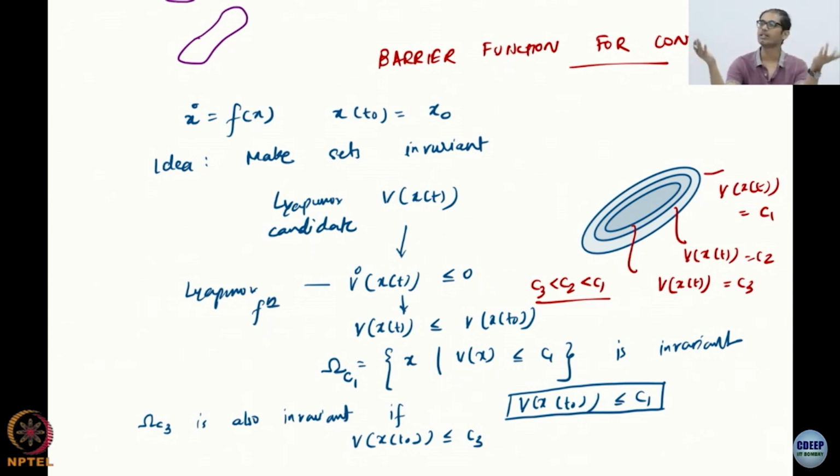Typically, how do you define your safety set or desired region of operation? You decide it, predefine it, you do not base it on your initial condition. Initial condition can be anything, right, but you do not base your safety critical set on where you started. So because of this kind of construction, you will always stay inside this set. So you are actually wasting the ability to work here, which might in some cases be what you desire actually. You might need more control effort to always stay inside. You might be allowed to get out and then come back in. That's okay, as long as you're remaining in the larger set, but this doesn't allow it.